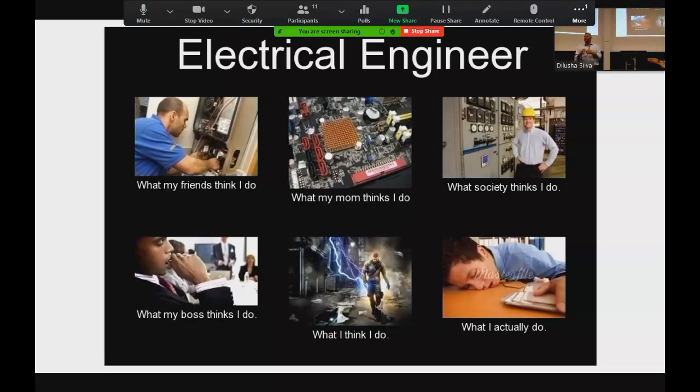Unfortunately, motors also tend to blow fuses. Yeah. Because their startup current is huge. Whereas with a circuit breaker for a motor, it can draw a lot of current, and the circuit breaker won't trip because it's got to draw that current for a sustained period. But yeah, you can go out and buy a circuit breaker of the same rating, say a 100 amp breaker, or say a 63 amp breaker, and you can buy a type A, B, C, and D. A is very, very unique in Australia. We don't tend to see them at all. B's and C's are the most commonly used, and a D is a motor rated breaker to allow that let-through current and then to operate.